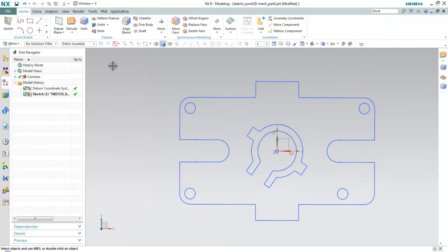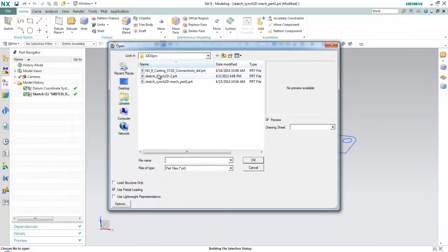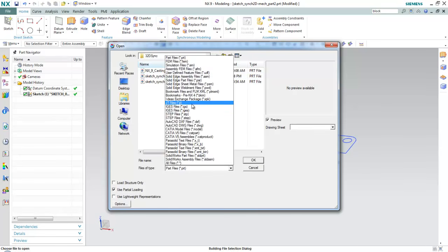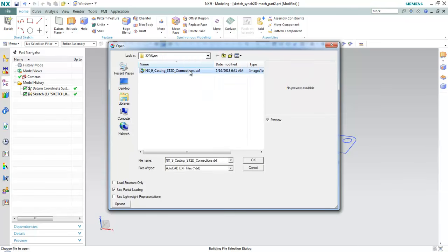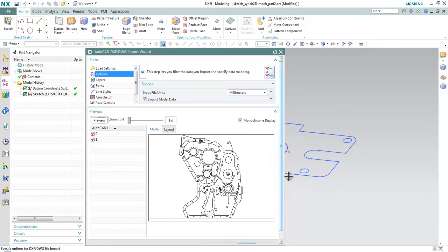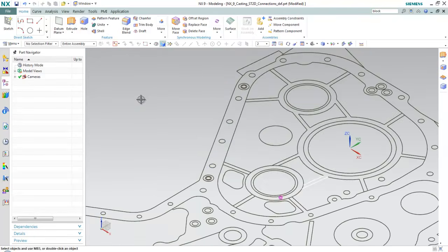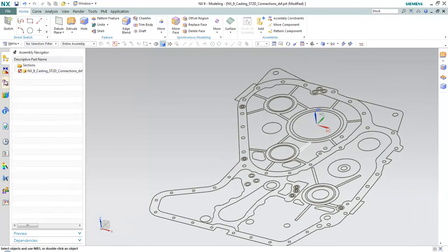Now you may be looking at that and saying, well, that's geometry that I created in NX. Why would I use that? Okay, and obviously you can still continue to use all your sketch methods. There's just sometimes that might make it a little more flexible to edit, especially how we rotated that center item. But where you may use it more is something like this. Right? I have this DXF. I'm going to bring it into NX. Right? You can see the preview of it. I'm going to bring it into modeling. Okay, so I have this curve geometry in here. I'm going to go ahead and create a sketch.